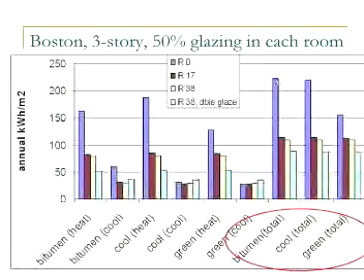Now, at the same time, we can say, well, let's just stay with the black roof and let's add some insulation to an insulation level of about R17, which is about 2 or 2.5 inches of foam insulation. And you notice how much the total energy use has gone down. This is this red bar here. Now, if I do the cool roof and R17, that's this red bar in the second cluster, and you can see there's almost virtually the same result, which is telling us that if I'm starting out with a building which has very little insulation, insulating the roof of the building has much bigger effect on the energy efficiency than putting a cool roof on.